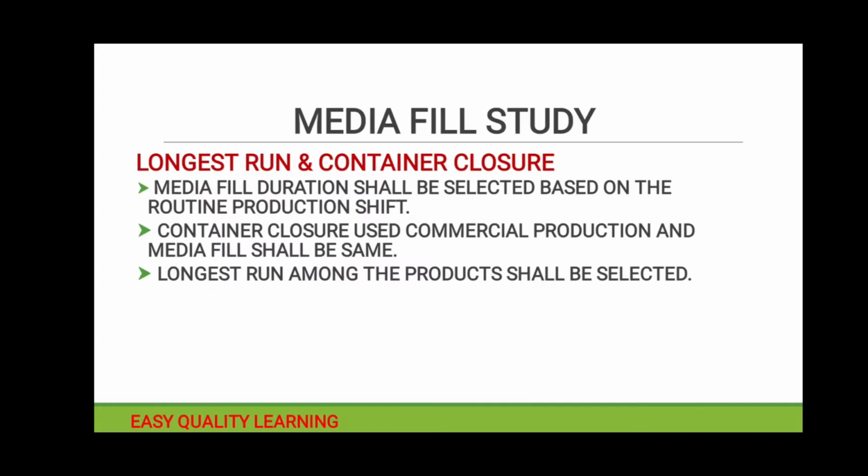Longest run and container closure. Media fill duration shall be selected based on the routine production shift. If our production is running in 1 shift, 2 shifts or 3 shifts, based on that, whatever is the longest run for that particular container closure system, we need to consider for the media fill, so that the shortest duration as well as the longest duration can be accommodated in the media fill activity. And the container closure which is used for our commercial or production activities, the same container closure shall be considered for the media fill activity. Then longest run shall be selected, which we have already discussed.